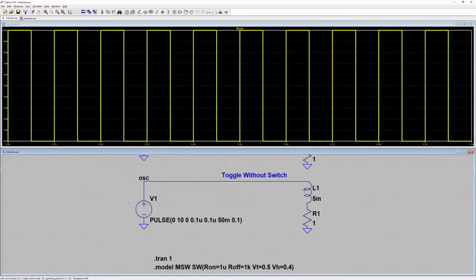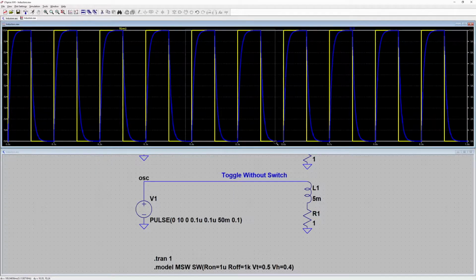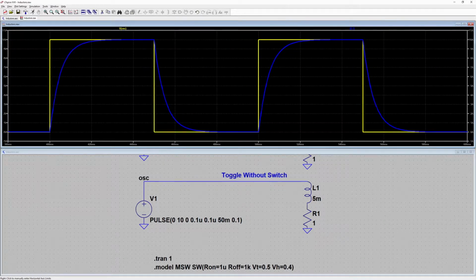Remember, an inductor is a bunch of loops of wire wrapped around something that channels magnetic flux. Air can channel magnetic flux for an inductor, but it doesn't do this as well as other materials can. When we see 10 amps flowing through L1 and R1, we know that the inductor isn't adding any significant resistance to the circuit. Since the effective resistance of the inductor is not always the same value, we should, and will, call it impedance. The impedance of an inductor varies with changes in frequency.